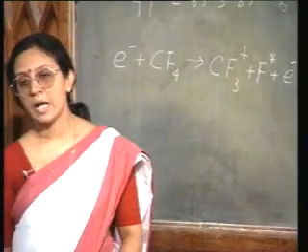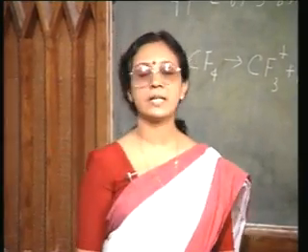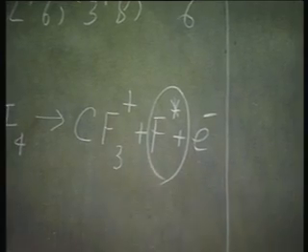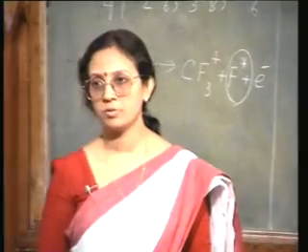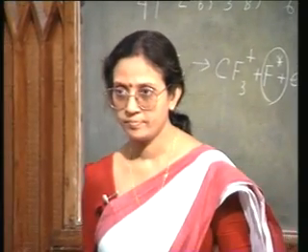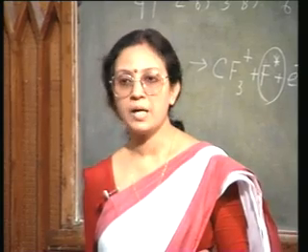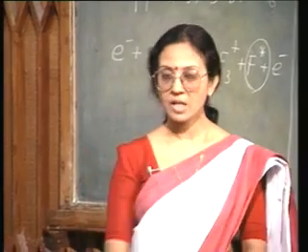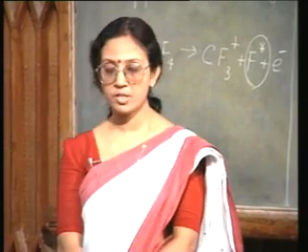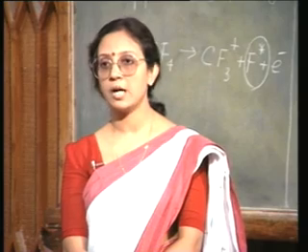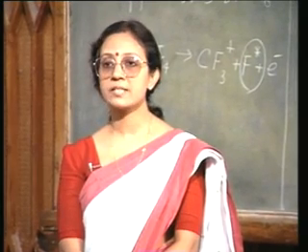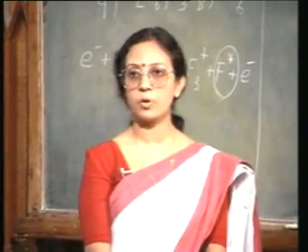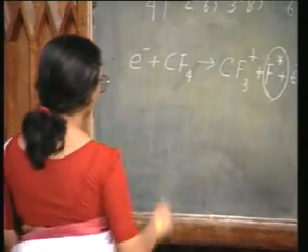Now, for silicon etching, this is the most important item. Silicon is etched by this free F*. This is the primary active species which is going to etch silicon. And how does it etch silicon? It reacts with the surface atoms of silicon and forms a volatile product, SiF4.